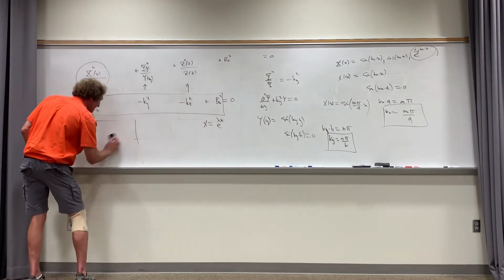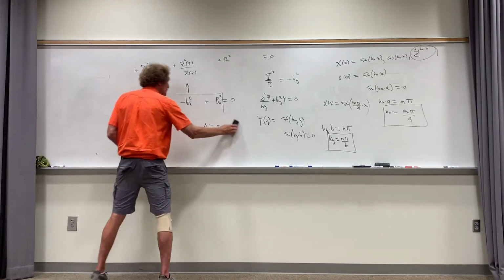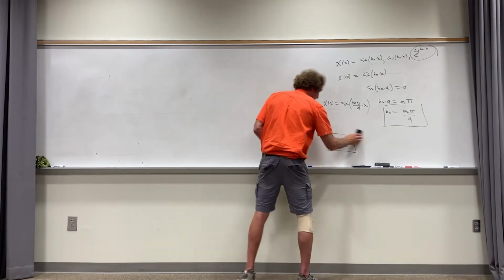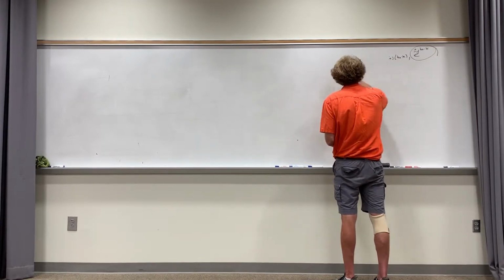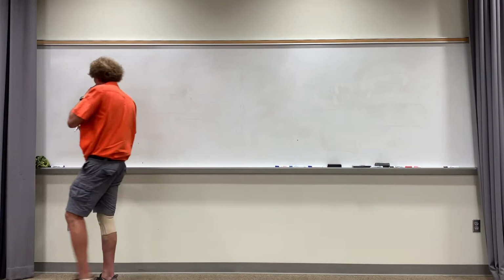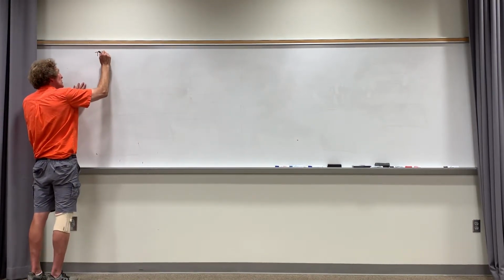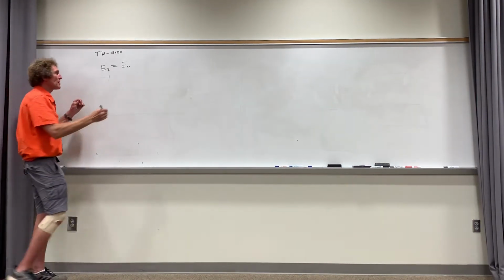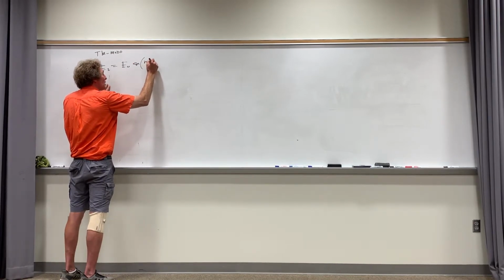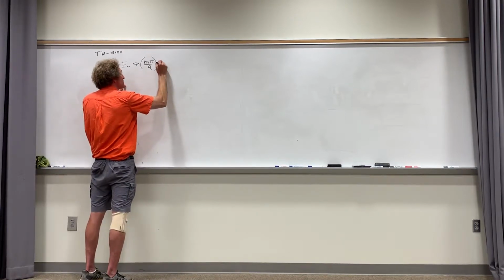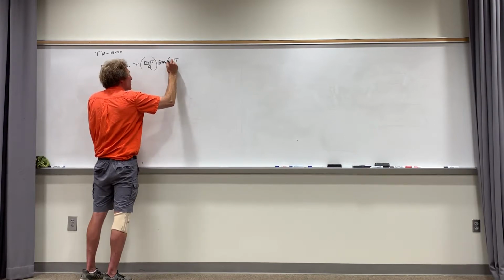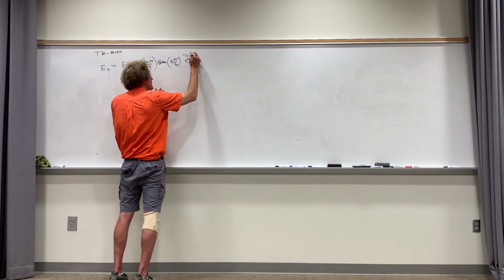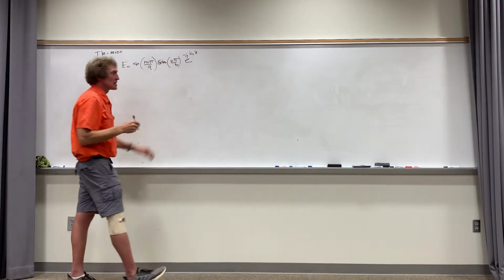And that all said, let me just write the final form of this. So now, when we take all these forms of x, y, and z and multiply them together, just like the separation of variables says we are to do, this is laid out in his book. He doesn't do it quite the way I do it, and I'll try to explain. I mean, he does, but I use kz there. Now my general form for Ez, this is for the TM mode, is going to be some constant. So just write E naught here. It's some scale factor. And it's going to have a variation as sine of m pi over a times sine of n pi over b, where m and n are integers, times e to the minus j kz times z, and that's the E field in the z direction. I'm going to explain kz in a second.